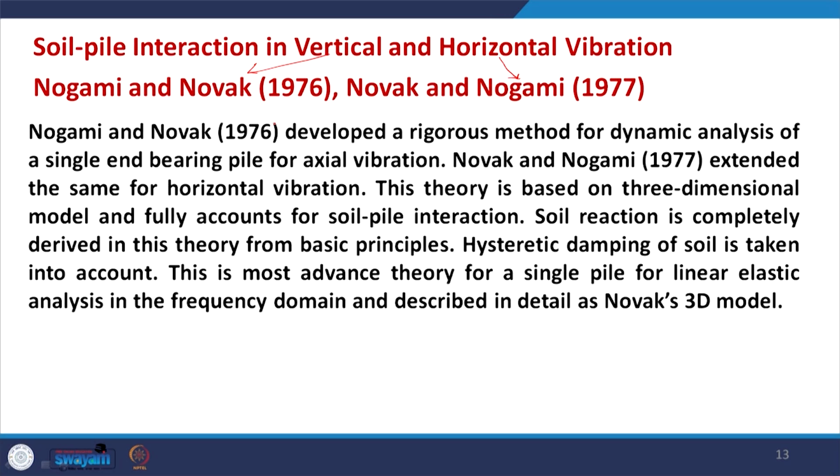So, it is difficult to account for soil pile interaction because only a discrete model has been considered. Soil reaction is completely derived in this theory from basic principles. Hysteretic damping of soil is taken into account. This is the most advanced theory for a single pile for linear elastic analysis in the frequency domain and is described in detail as Novak's 3D model. Later on, this theory which we are going to discuss in the next slides will be treated as Novak's 3D model. So, this is the most advanced theory for a single pile for linear analysis.